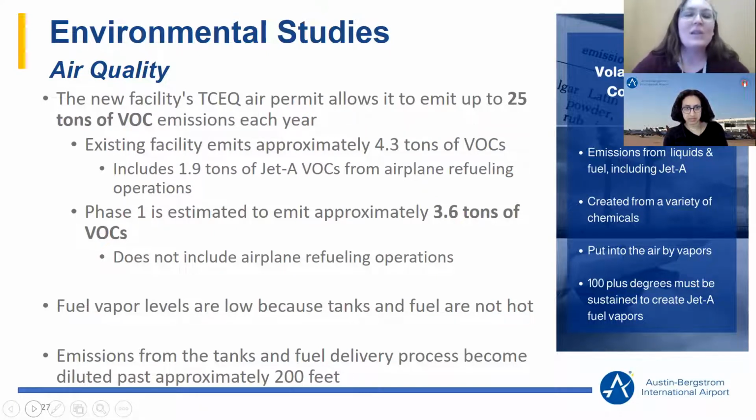Okay, so what I'm going to do is talk you through the environmental studies that were conducted recently. The airport hired a third-party independent firm to conduct some modeling and some air quality studies to help us understand what the emissions will be for not only the current facility, but for the new facility. So first, I want to talk a little bit about the TCEQ. The facility's air quality is guided by the Texas Commission on Environmental Quality. The TCEQ makes sure that the facility will not exceed 25 tons of volatile organic compound emissions a year. And when we say volatile organic compounds, what we mean are the emissions from the jet fuel.